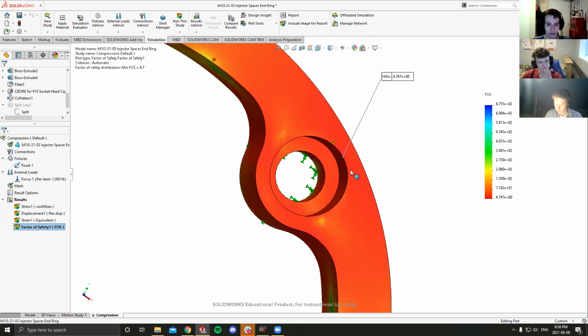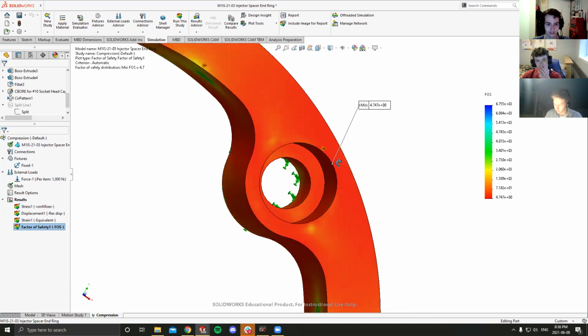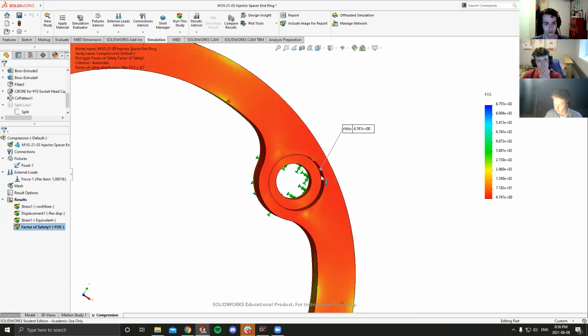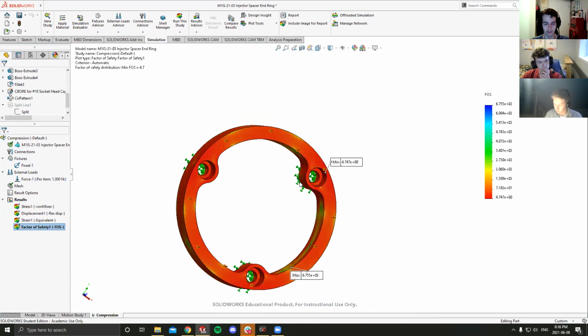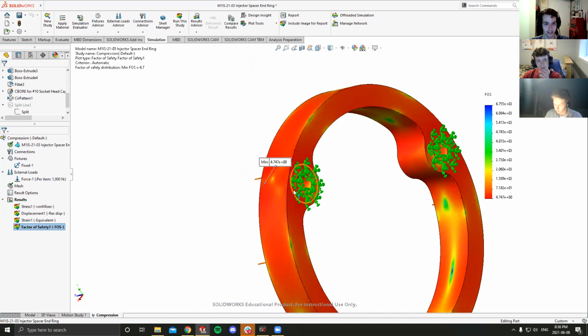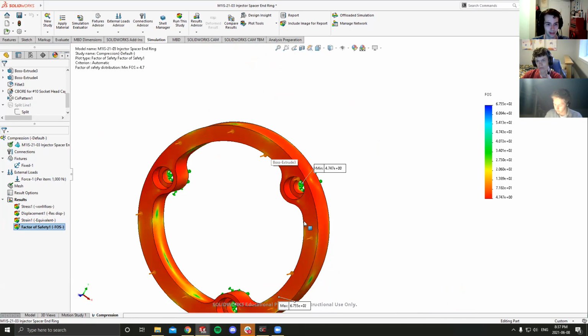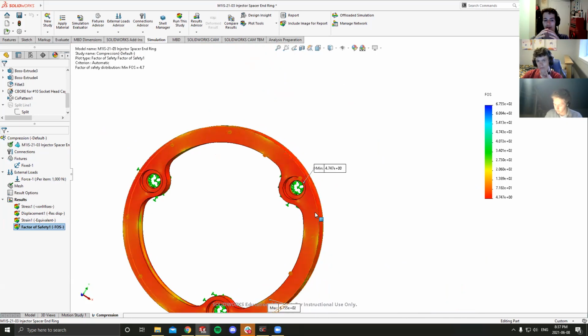However, even then, for this section of our end ring to yield first is pretty inconsequential, thinking about how the back of our end ring is contained by our posts, and the outside of our end ring is being held by our combustion chamber.